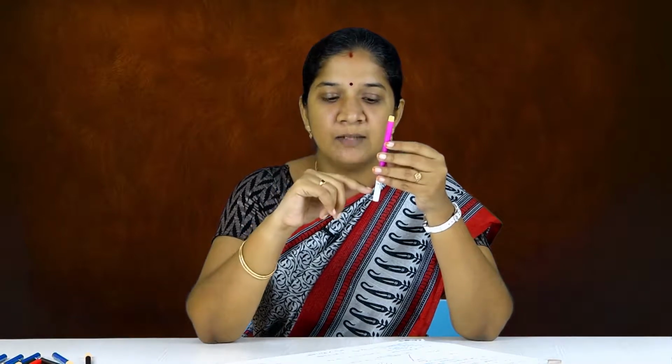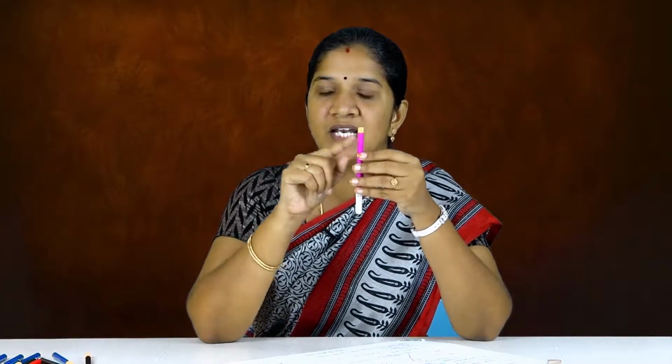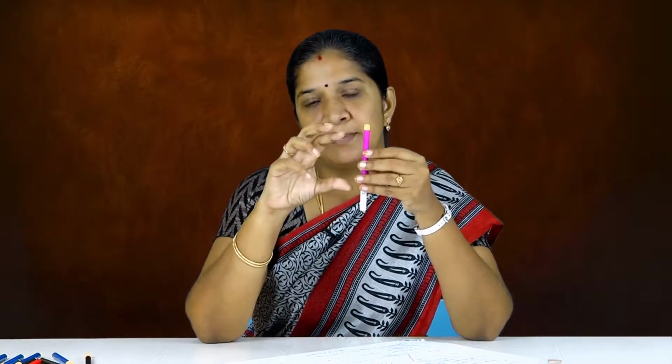You may ask some questions like this. You can say singly reinforced means providing reinforcement only in this region, not here. You may have some doubts like that. The answer is that providing steel in the tension region is the main motto. But I won't say that I won't provide any reinforcement here. This reinforcement won't take care of tension.